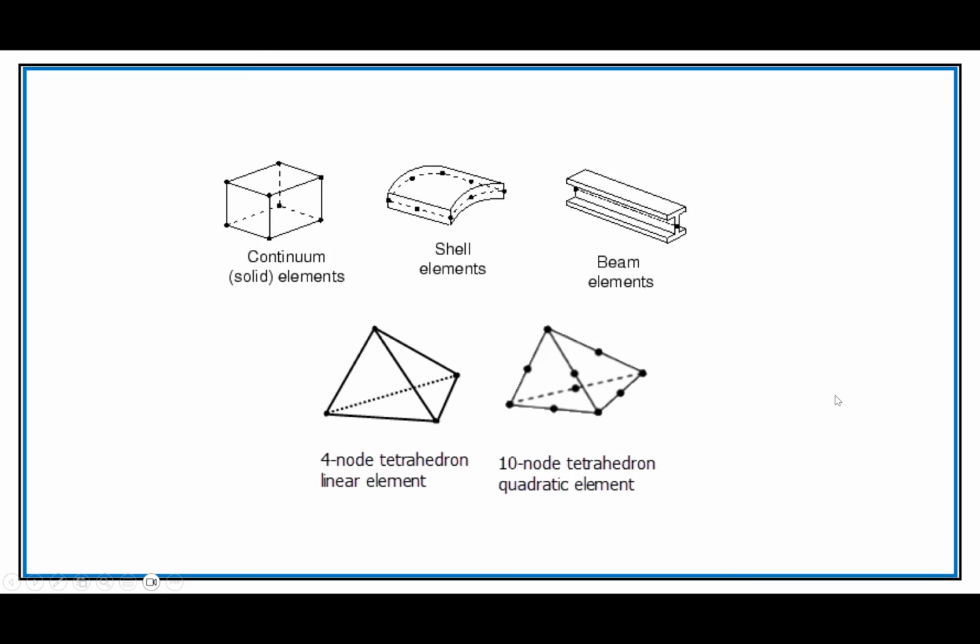There's some more of the same things I just mentioned about different element types, especially the shell elements, the plate elements. They often will have these nodes onto the sides of them. The biggest problem is joining plates together or joining plates with other elements and making sure that the sign conventions of the nodes adjacent to each other in transitions aren't counteracting, so they're having incompatible sign conventions.